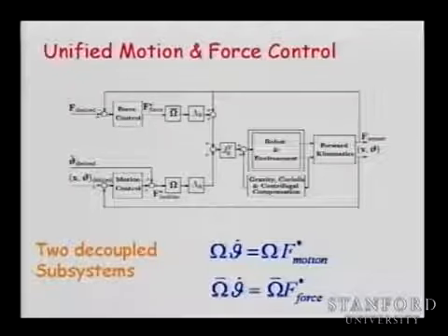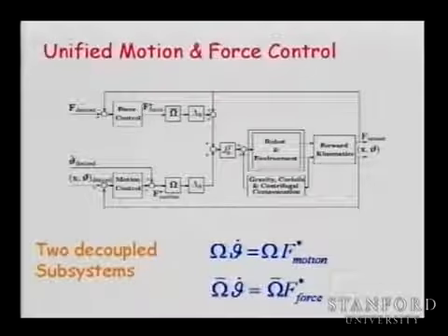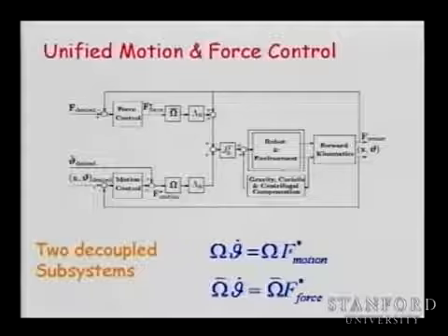So this is maybe the beginning of the introduction of advanced topics that we will see. I'm going to continue with this discussion, but you have really to deal with this very important problem. If you want your robot to interact with the world, you need absolutely to be able to control the contact forces. And contact forces doesn't mean only linear forces, but it also means you control moments. And with moment control, you are going to be able to achieve a lot of things.